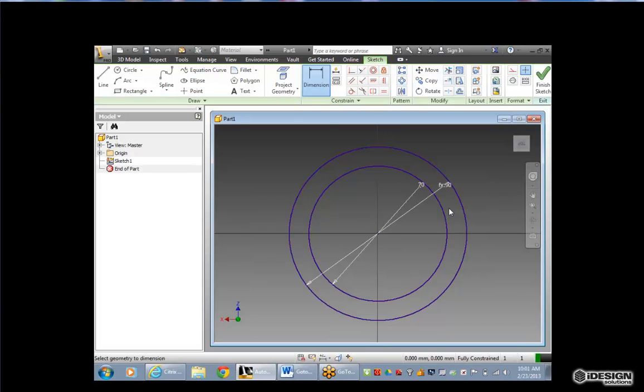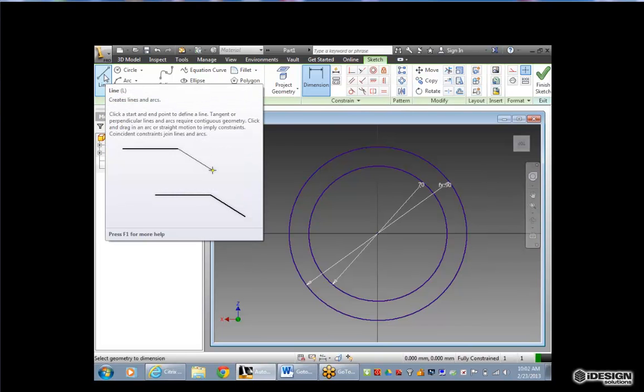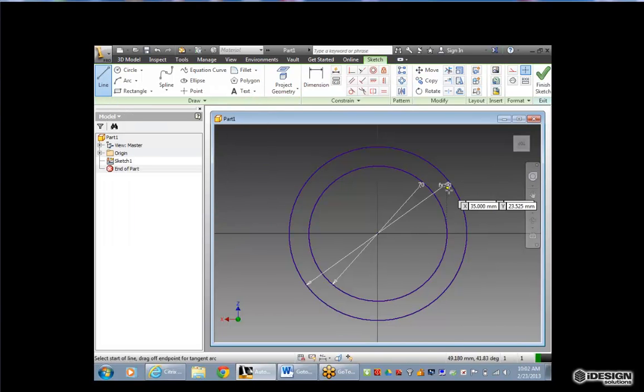That's correct. Okay? And then you put the spoke on before you went any further, right? That's correct, yeah. This way, it keeps it all in one sketch, and it makes it nice and easy if you do need to update anything in the future. So you ran out, and then did you click at a point? Did I pick a point? Yeah, so the next click will place that line, and now you hold your left mouse button down to start that arc. Ah, yes, and then we wrap around to 180 degrees, and then finish.